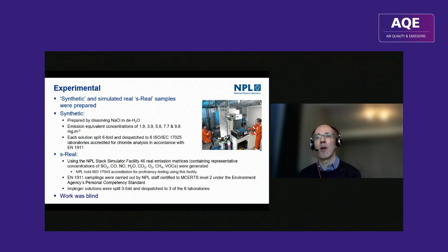If you were to multiply by the volume and divide out by the amount of cubic meters of gas you'd normally sample from a stack in about a 30-minute run, you'd get the following emission equivalent concentrations detailed there. So that's our 0 to 10 milligram per cubic meter range, and it obviously makes things easy to look at in those units. Those 5 solutions were each split 6-fold and dispatched to 6 17025 laboratories accredited for chloride analysis in accordance with